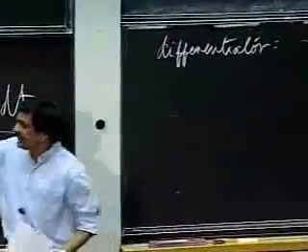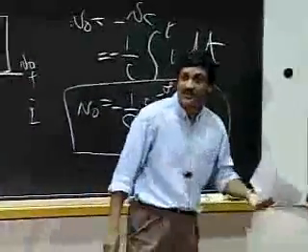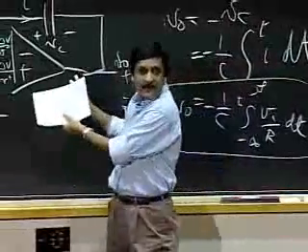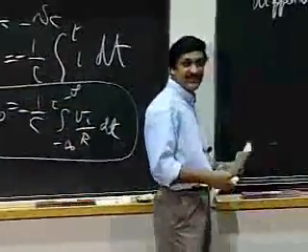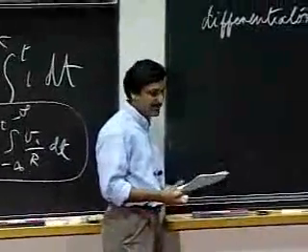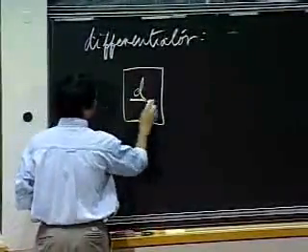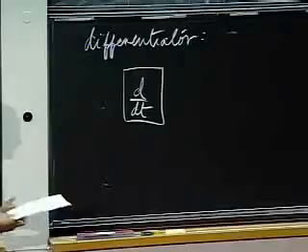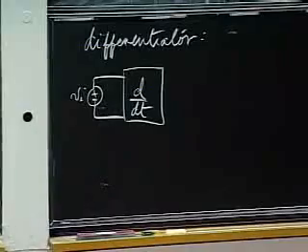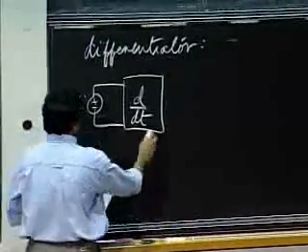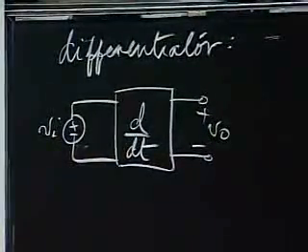Okay, so now that we built the integrator, I could give this out as a homework problem, and you should be able to design a differentiator based on what you've learned here. You now have the tools to go and do some design like this, but we don't have any more homeworks left, so I guess I'll go ahead and solve this for you right here. So the building block that we need looks like this: d by dt here. Let me take a VI and stick a VI in there. That's what I want to build.